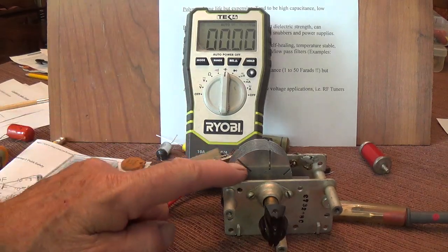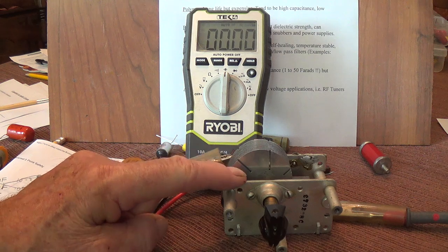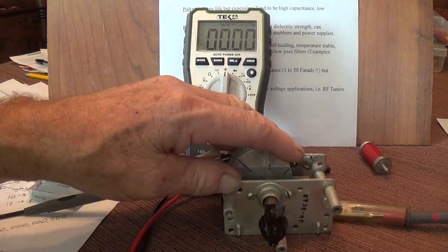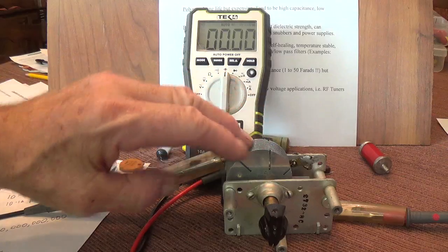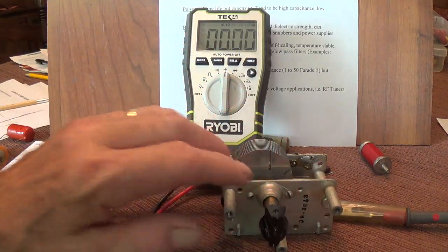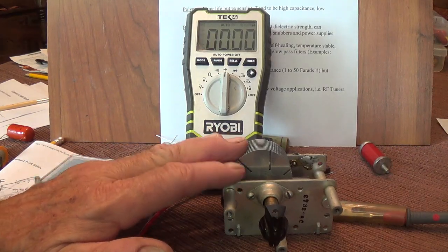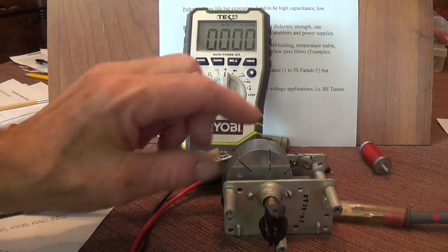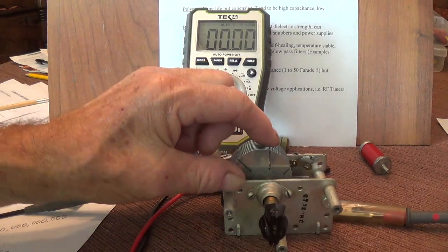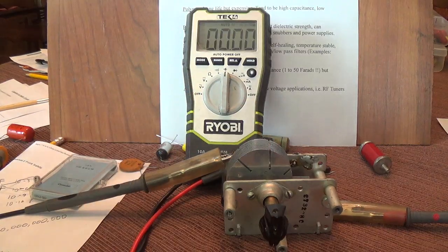This is also a great device if you want to fine-tune your tone circuits. If you have one of these, you can connect it into your amplifier tone circuit and dial in the exact capacitance that sounds best to you on your tone controls, and then read what that capacitance is, and then install a fixed capacitor of that value in your tone circuit.